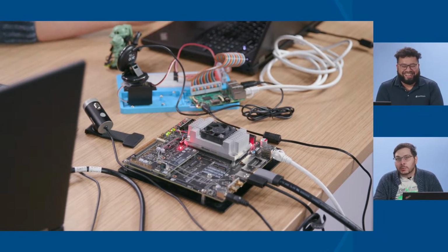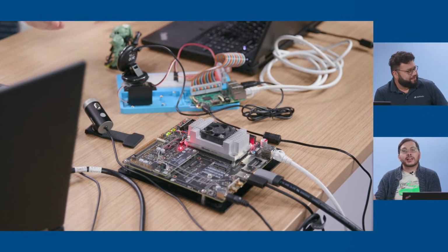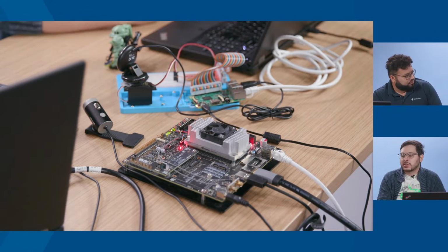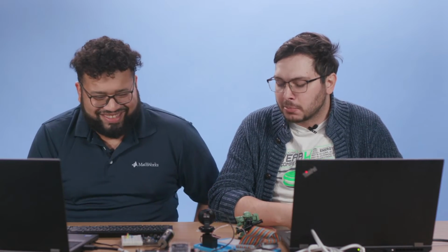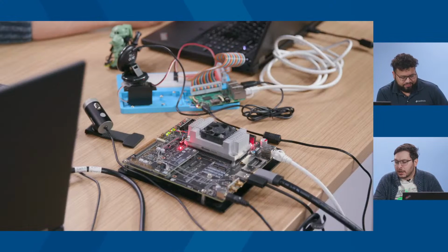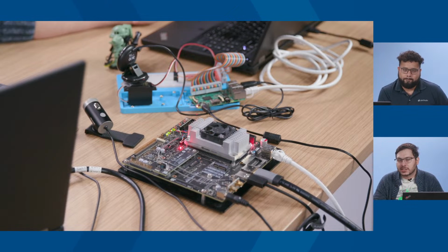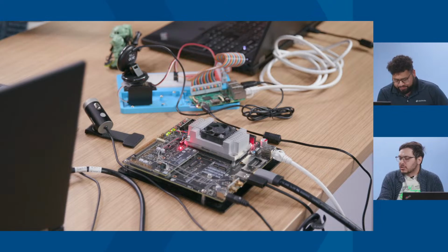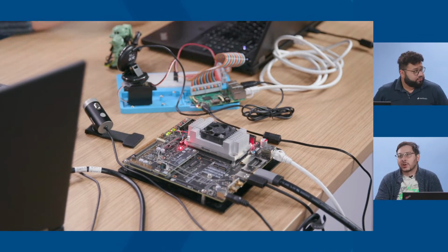What we're going to do is take our MATLAB code or our Simulink model, and generate C code that we're then going to deploy onto our embedded device. Mostly because it's nice and flashy, we've got a couple webcams hooked up, one to the Pi, one to the Jetson here, to demonstrate some computer vision stuff, because it's the easiest thing to take from working with it in simulation to working with a real camera on my hardware now, right?